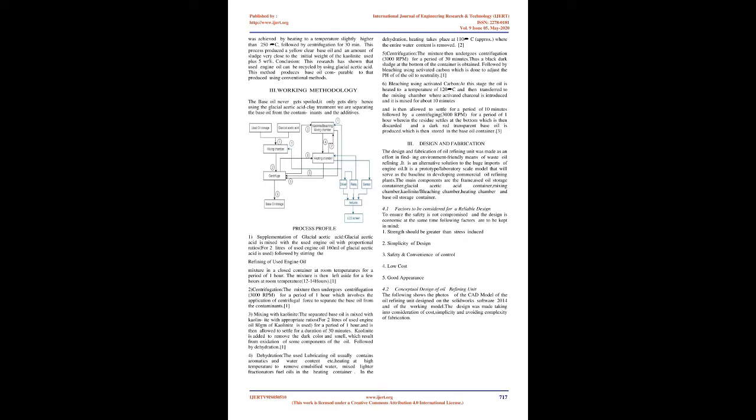Conclusion: re-refining of waste lubricants could result in both environmental and economic benefits. Re-refining of waste oil to manufacture base oil conserves more energy than reprocessing the waste oil for use as fuel. The energy required to manufacture re-refined oil from used oil is only 1/3 of the energy required to refine crude oil to produce virgin base oil. Therefore, re-refining is considered by many as a preferred option in terms of conserving resources as well as minimizing waste and reducing damage to the environment.